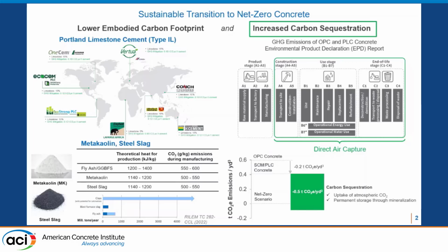And I have included here many limestone cements, PL3s here, PLCs here, from different companies. Also, I would like to emphasize here that limestone cements are by no means the same from the different companies. So we've seen percentages up to 15% as replacement of the clinker.